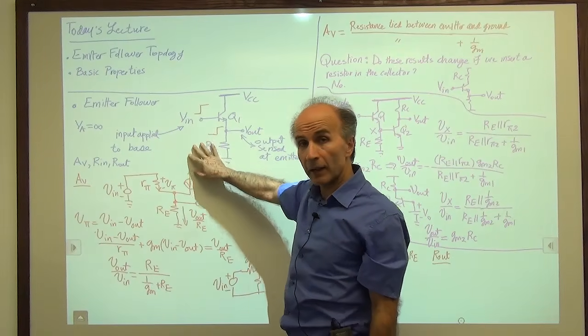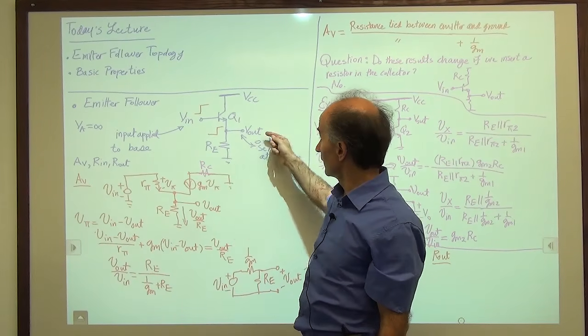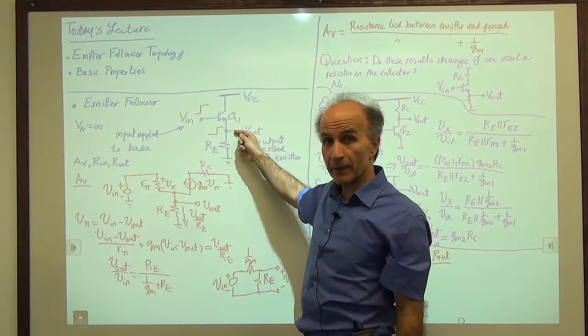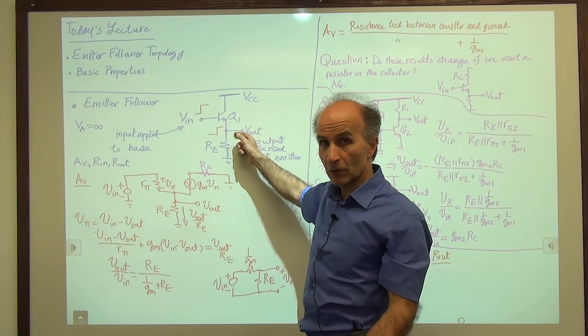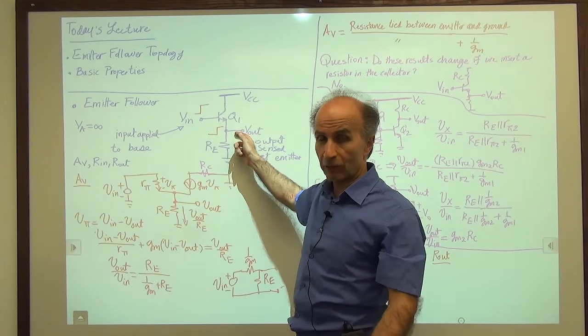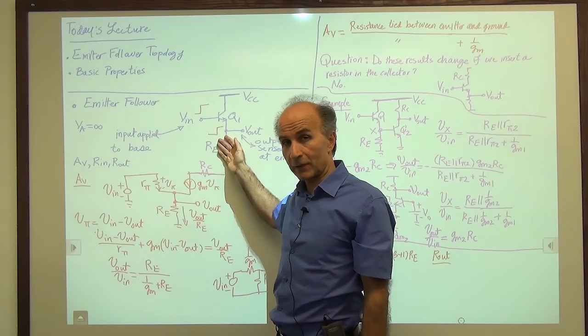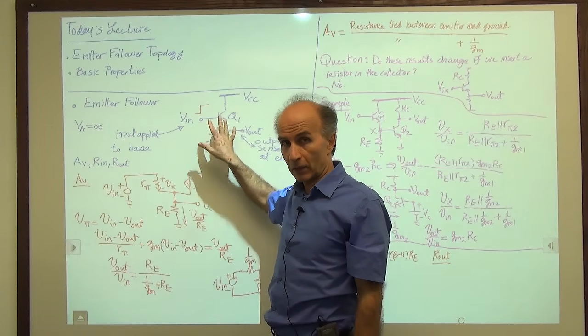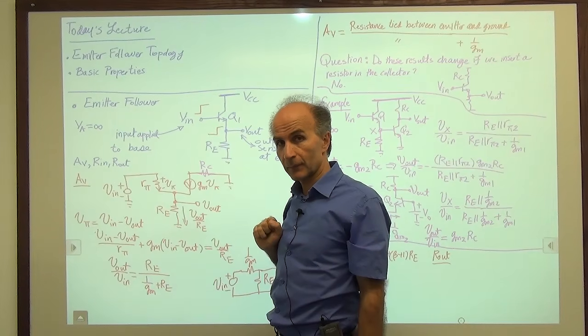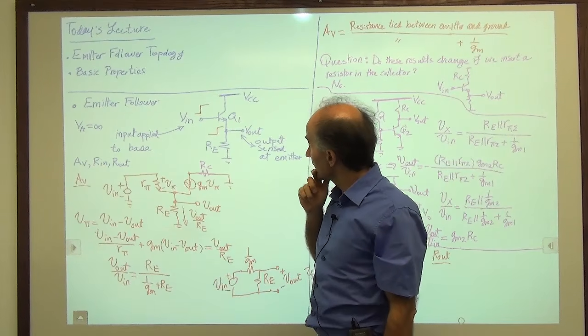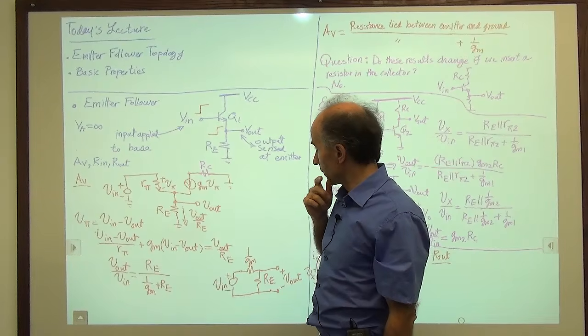Place this in a box and apply a voltage from outside, Vx, find the current Ix. That ratio gives us the output resistance. This is similar to finding the Thevenin equivalent of the circuit.